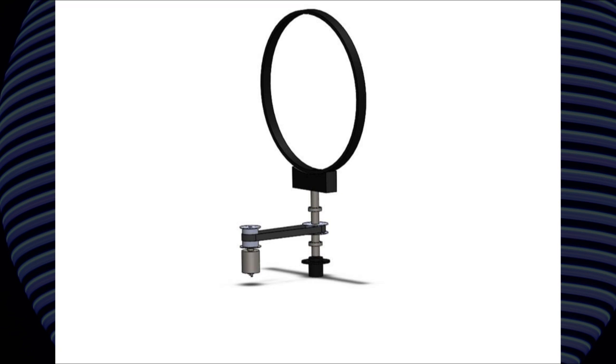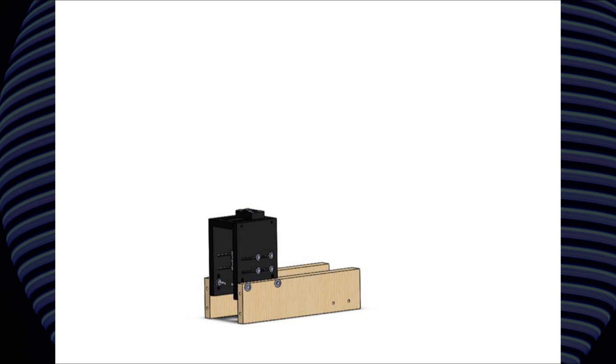As I said, the rotating part of the globe is driven by a motor thanks to a belt. This motor must be held to the structure so as to optimize the globe rotation. For that, we designed metallic presses. To decrease the impact of the belt tension, we extended the motor's axis above the pulley and put a ball bearing on it. The whole system can move on a rail structure so as to set the driving belt tension or to correct the pulley's alignment.